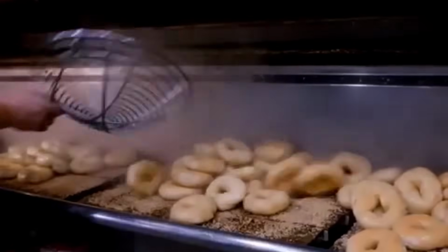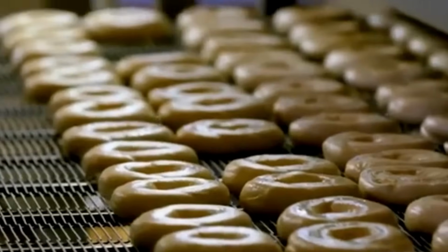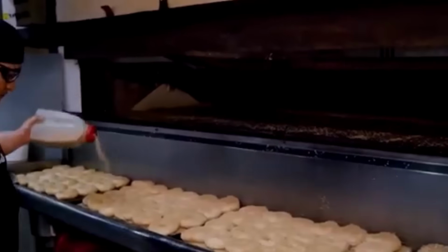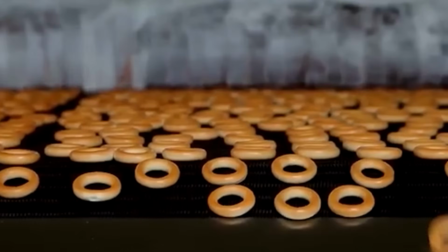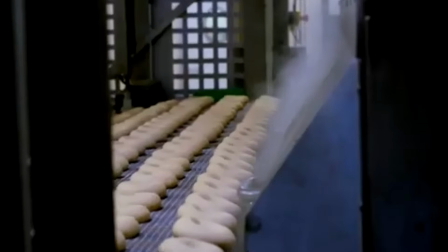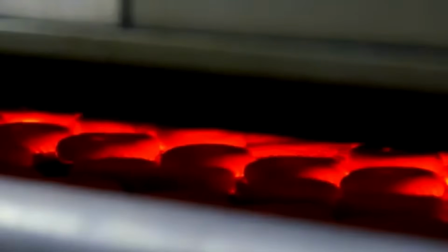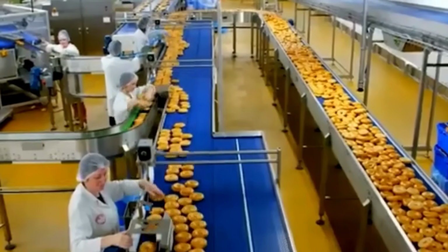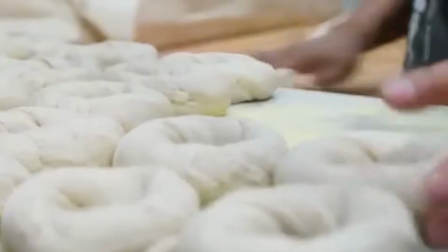At this point, the dense dough is released through a bottom hatch and fed directly into a portioning unit that slices it into thick, consistent strips, each one calibrated for weight and volume by servo-guided sensors that track the length, width, and compression of the dough strand as it moves forward on the belt.